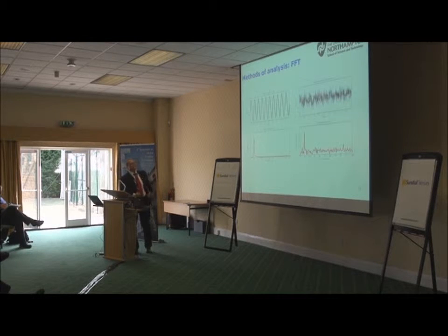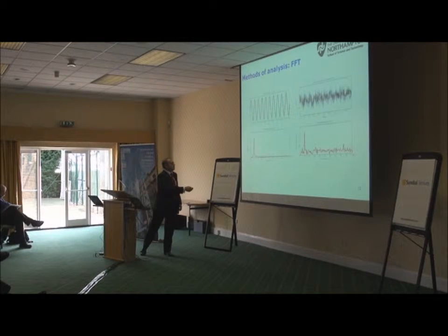So here's a quick example of how we apply the FFT. There are two plots here. The left-hand side shows a very simple signal. This could be vibration of this mass on the spring, could be a car. And it moves like this, harmonically. It is sine or cosine. And you can clearly see it repeats itself, this motion, as I showed earlier on. When we do the FFT of this signal, we see here the amplitude against frequency, and here the amplitude against time, and from processing this signal, we get a peak, which indicates one frequency value.